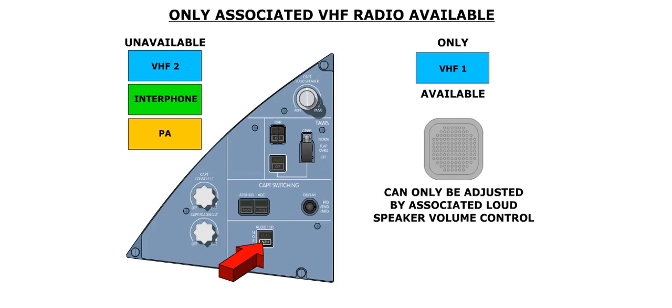In addition, the PA, interphone, and other VHF radio are no longer available on the captain's side. In either case, the audio on the affected side can only be adjusted by the associated loudspeaker volume control.